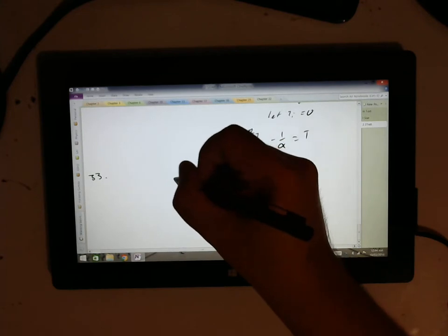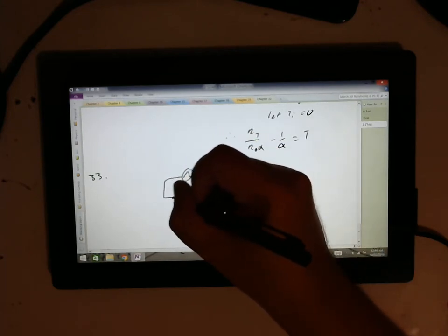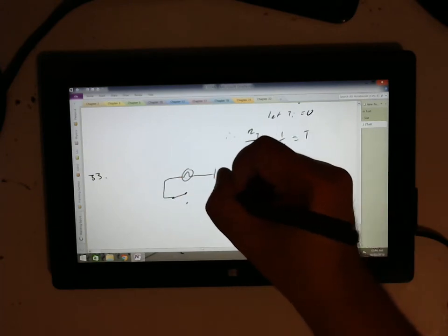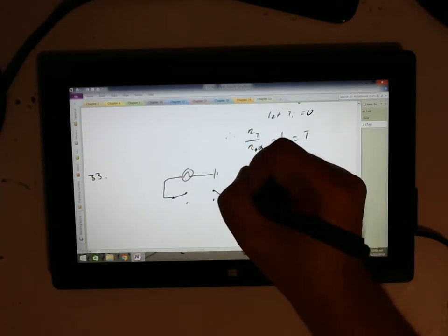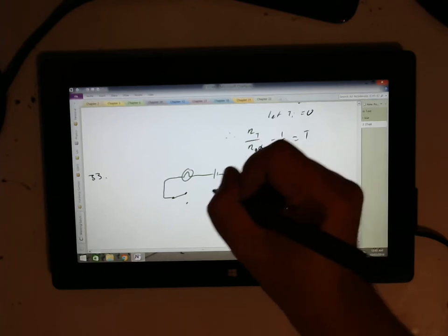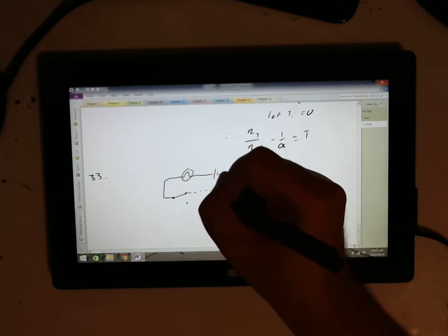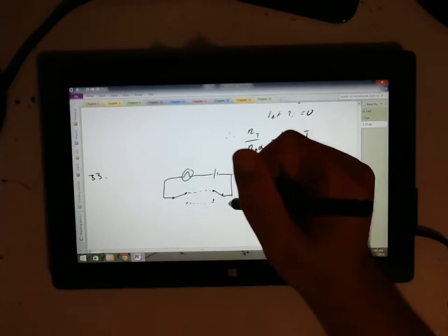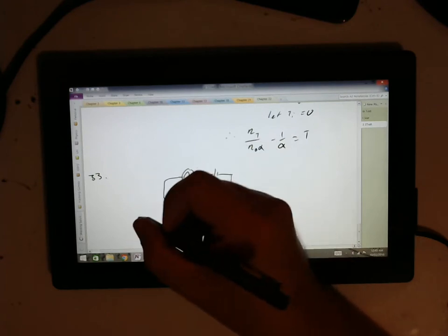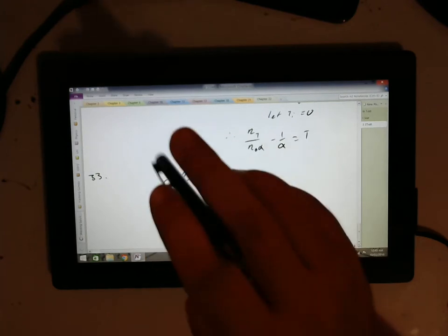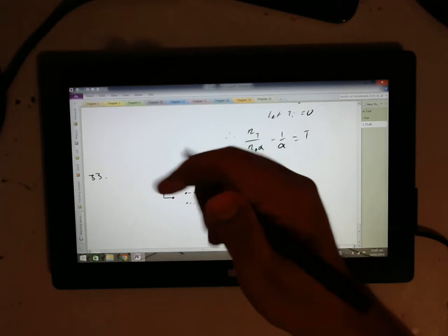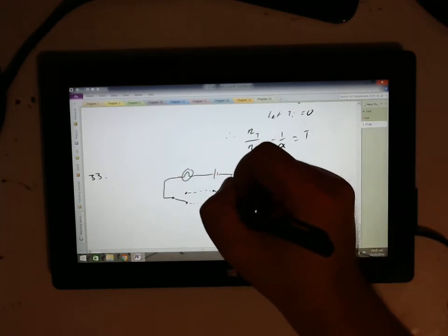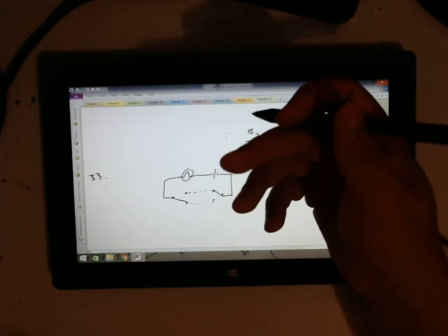Now the switching system for this is what we call a three-way switch. We need two three-way switches. It looks something like this. Now this one connects to here. I'm just going to do dashes for this so that we can see it. So right now this would be on. You get to one end of the house and you switch it to off so that this line here goes down to here, and we can see now the electricity doesn't flow, so it would turn off.